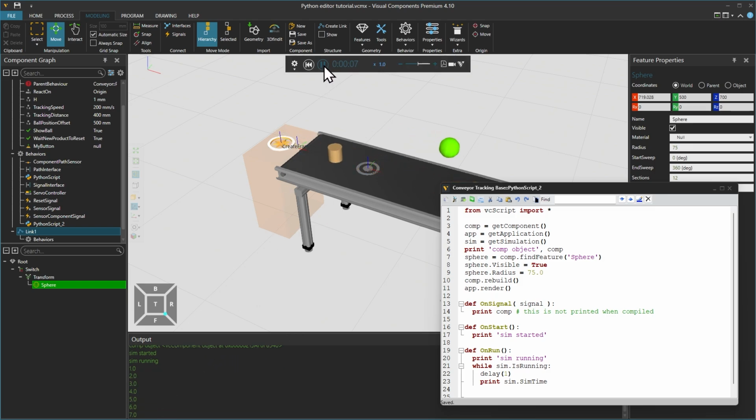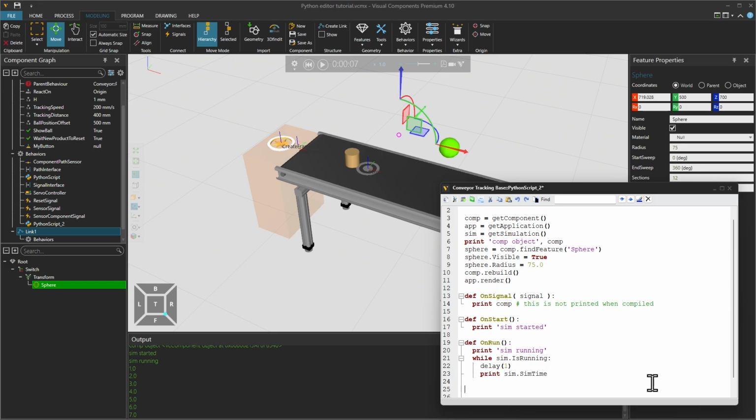Then pausing the simulation. Another common event is to get a user's input on changing a component property's value. Let's create a simple example by writing a script to create a ball radius property and define a function reacting on the property value change. We will first use the snippet _property onChanged.